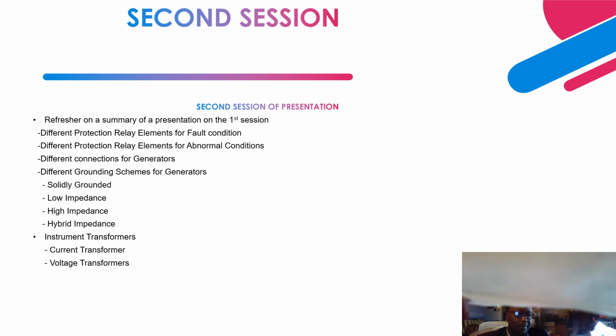Then we'll also talk about how these instrument transformers are selected, so we'll talk about saturation, and how to calculate the saturation level of these CTs.